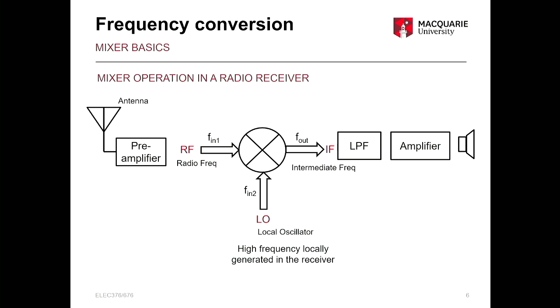So this is slightly out of scope, going to draw a block diagram for a communication equipment. That's beyond the scope of this unit. But if you look at that, you have the antenna, it goes to a preamplifier. So the antenna picks up the RF signal. If you're talking about FM, it's around the 88 megahertz to 108 megahertz band. You can't go lower or higher band because there are regulations for spectrum. So you can only use this much for broadcasting. Then the antenna picks that up and preamplifies, because the antenna picks up very little amplitude. It's not a strong signal.